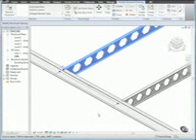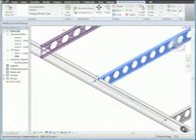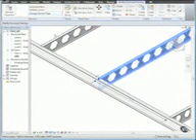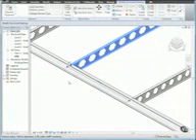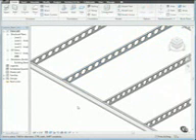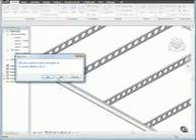Select one of the other castellated beams, and then click the Change Element Type drop-down and select CB 18x22 Custom. When you do, notice that the openings in the beam will change based on the new beam type. Clear the selection and close the file without saving it, as the next lesson will provide its own training file, and that concludes this lesson.